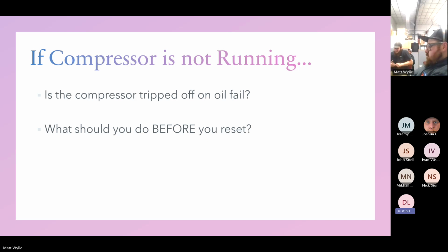Compressors aren't designed to have liquid in them. So if you've got liquid coming back to the compressor, if it's bad enough, it's going to push the oil out of the compressor and out into your system. Especially at supermarkets, you've got 20 different systems on a rack. All it takes is one of those systems flooding back to wipe out the oil in your compressor.